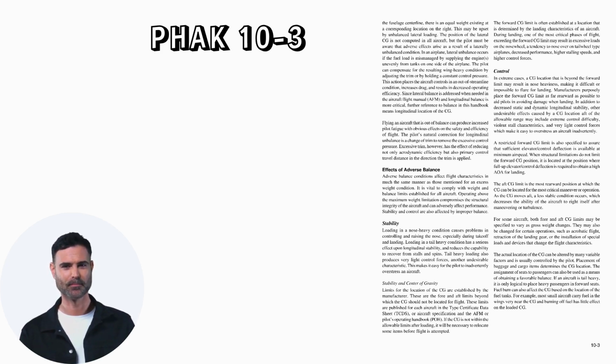Loading in a nose-heavy condition causes problems in controlling and raising the nose, especially during takeoff and landing. Loading in a tail-heavy condition has a serious effect upon longitudinal stability and reduces the capability to recover from stalls and spins. Tail-heavy loading also produces very light control forces, another undesirable characteristic. This makes it easy for the pilot to inadvertently overstress an aircraft.